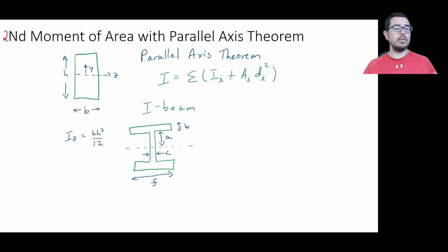The integral of y squared dA. We can essentially use addition, and some more or less simple algebraic expressions to figure out the overall second moment of area.